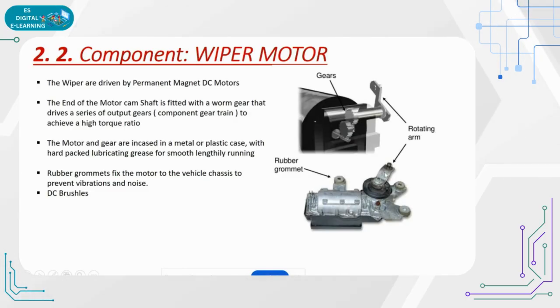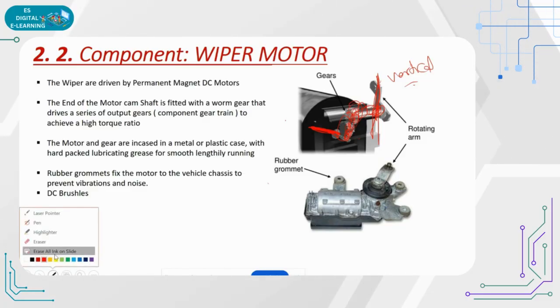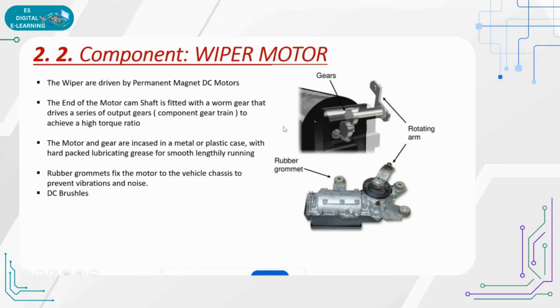So this is a motor, and it has an adjustment at the back side. If you go inside, this is the horizontal if you see. For making the vertical alignment, inside it has a gear system interlinked. When it is interlinked with this, with the help of some knobs, this will move with vertical rotation. So this is horizontal, this is vertical rotation. The wiper motor helps to rotate in such a way that the wiper system can move.